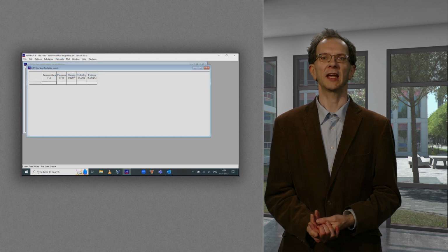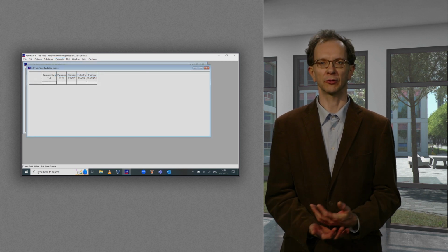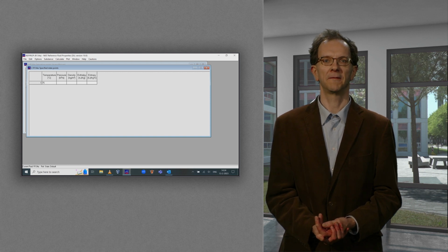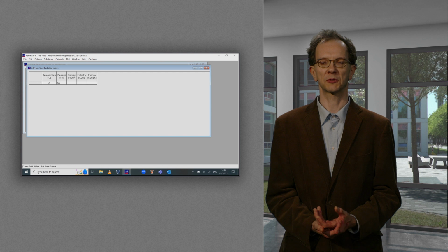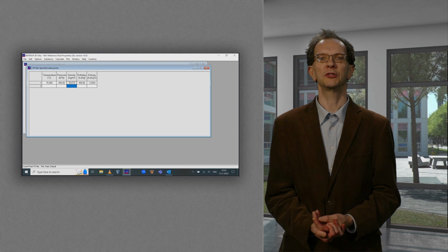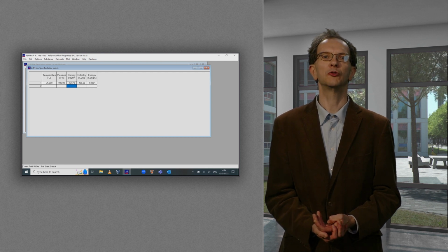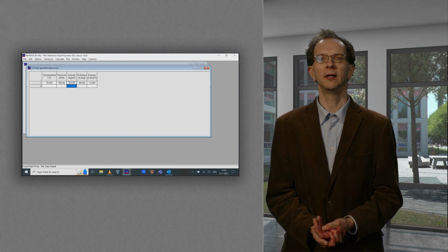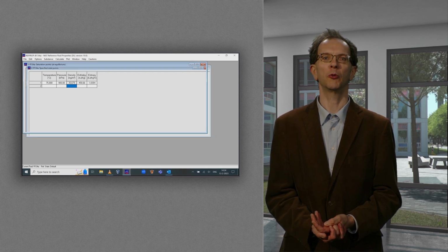The conditions at the end of the compressor are also given, 900 kilopascal and 75 degrees Celsius. We go to the table of the specific state points and we fill in the temperature and pressure, and we obtain the enthalpy at point 2, which is equal to 458.66 kilojoule per kilogram. We assume that there is no pressure drop in the condenser.